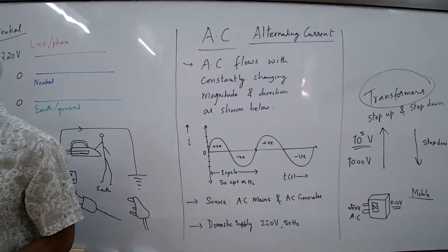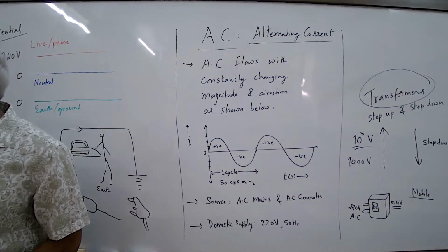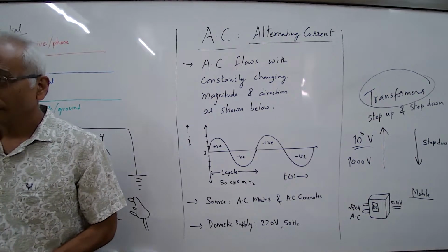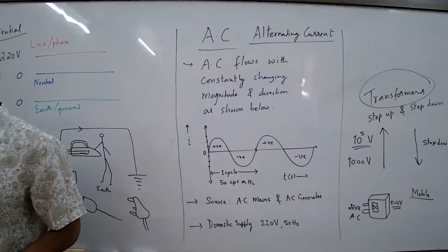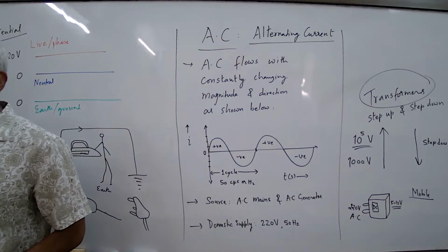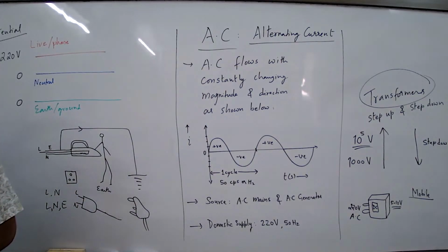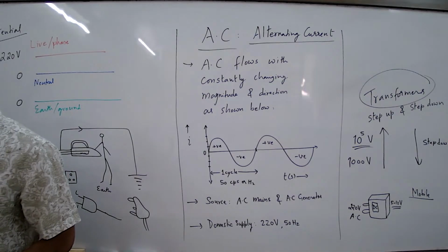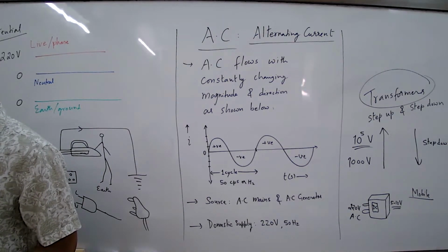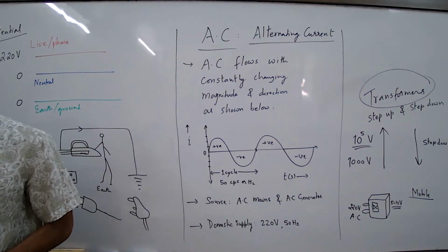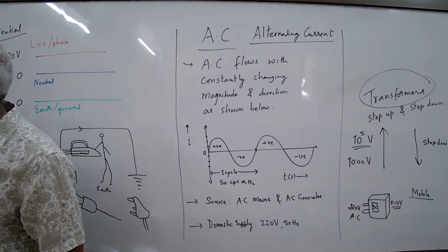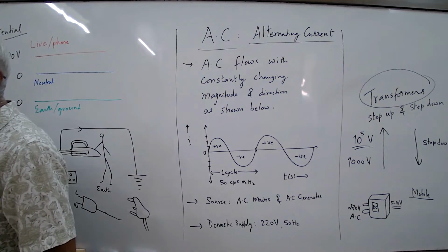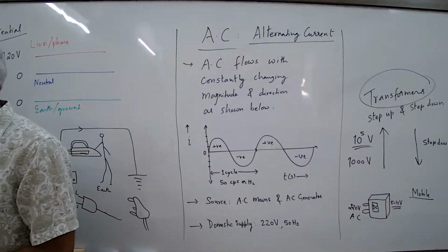This is the distribution code. Like, this is a society with only three flats. Each flat has its own fuse. So there is a fuse at the society level, the main fuse, and then every flat has its own fuse. The supply is shown for only one flat. If you have one more room, you can pull this wire further and go on connecting. The entire connection in our house is in parallel.